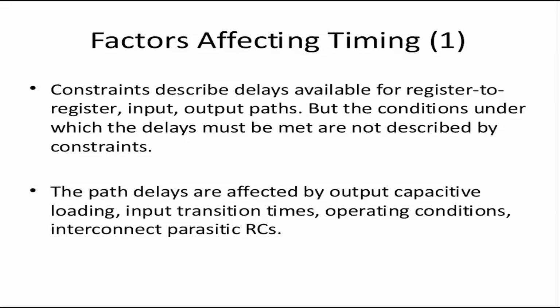because all the delays of the design depend on the capacitance. For example, the delay of a gate depends on the capacitance the gate sees on its output. That capacitance will be comprised of the inherent gate capacitance plus the net capacitance plus the fanout capacitance. Plus, it also depends on the input transition time. It depends on the voltage, the temperature, the process we are talking about, and so on. So in this lecture we are focusing on the second thing: the environment conditions. This is what I mean by the environment conditions.